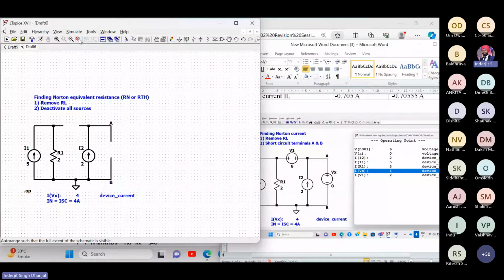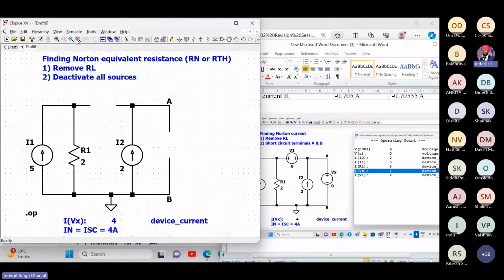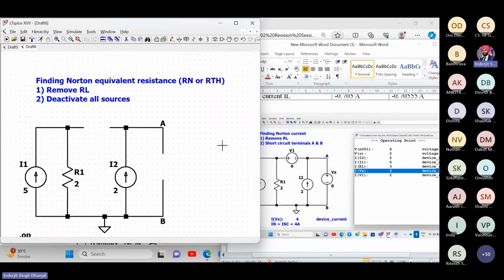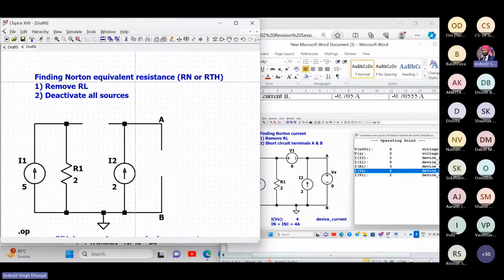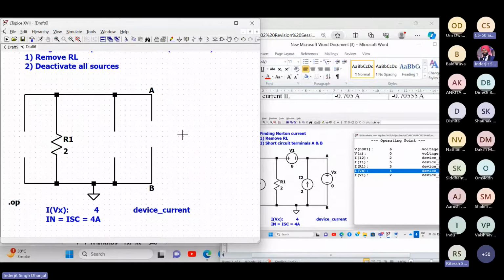So we can actually directly get that value, no sweat. Like this, see? This voltage source, I have removed it and replaced it with a wire. There are two current sources. I'll just remove them, open circuit them. Now tell me, what do I get? What is my equivalent resistance? Can you not see? It's R1. How much is it? Yes, sir.